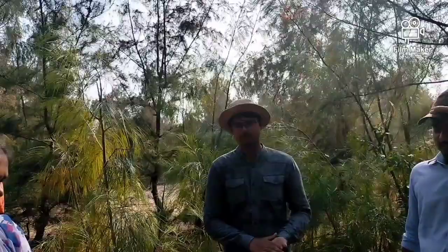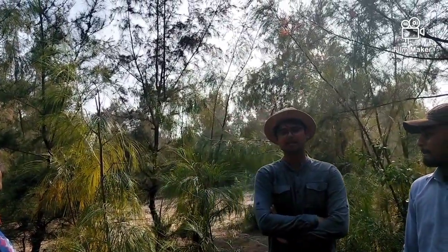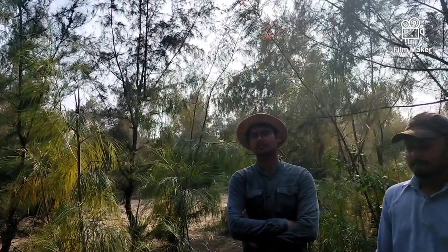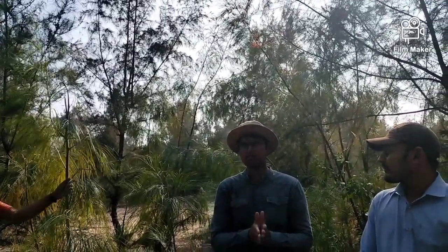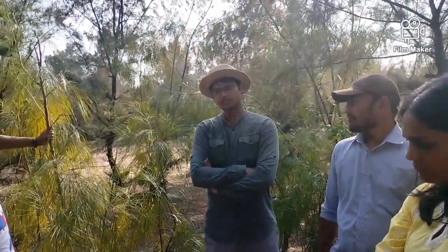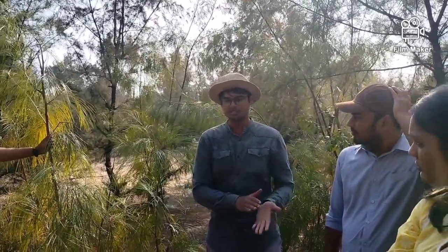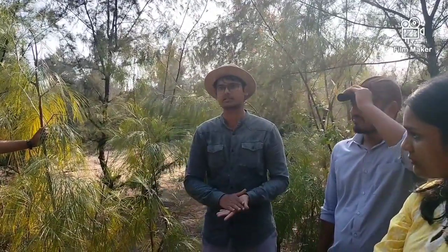People also use this for reinforcement, like how the reinforcement is laid in the concrete in the subsurface. For that we use a very high frequency, 1000 megahertz, because in that case you need very high resolution and less penetration depth. So for reinforcement you just use the higher frequency. Archaeology people also use GPR. Military people also use GPR to identify underground mines if there is something down there. GPR has a very diverse range of applications. So based on what you want to do, you have to select a particular frequency.